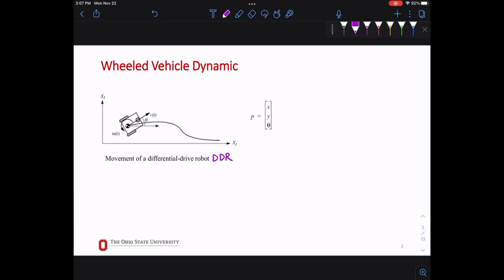And you see that if you draw a velocity vector here, if this is the velocity of the car, from the center of the mass, perpendicular to the chassis of the car, the angle that builds with the frame of the robot will be your theta, right? So when you rotate, you can calculate that.